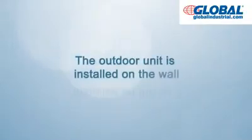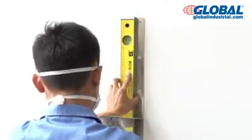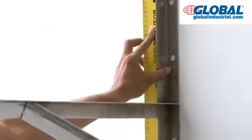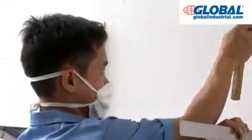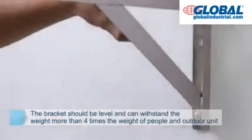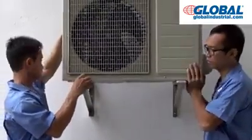The outdoor unit is installed on the wall. Confirm the position of the bracket holes with a level meter. Note that the bracket should be in a vertical plane. Fix the mounting bracket of the outdoor unit. The bracket should be level and can withstand more than 4 times the weight of people and the outdoor unit. The outdoor unit should be placed levelly on the mounting bracket.